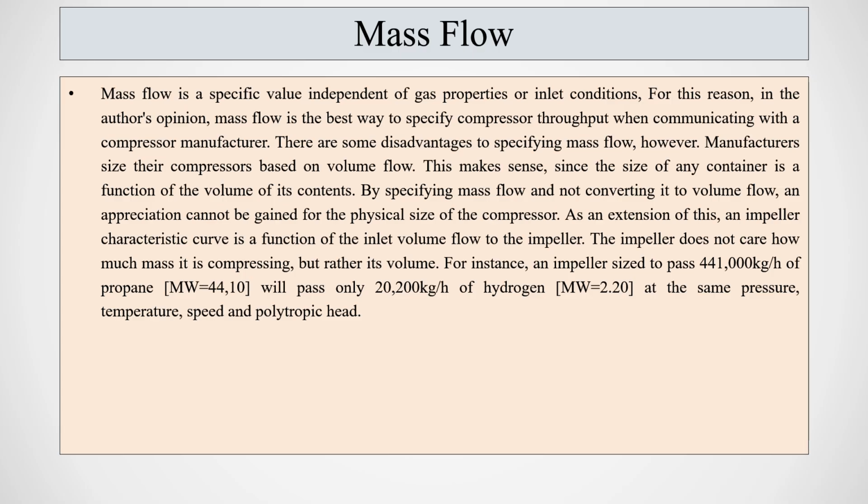Suppose for higher molecular weight, it will go nearer to your surging point. For lower molecular weight, it will go to your stonewall point. Same thing for compressibility factor, similarly for volume ratio, similarly for suction pressure and temperature. You have to be very careful while running a compressor.